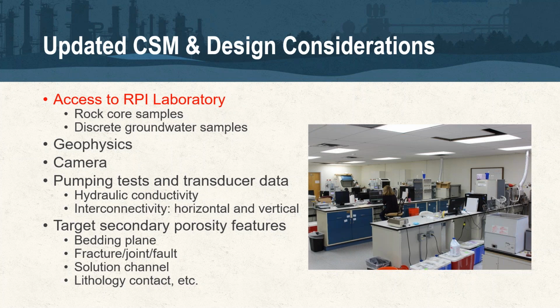And really, at the end of the day, this sets expectations. Unlike overburden sites where you can move over and continue to probe, you don't have that ability here. So going through the RDC and selecting advantageous places to put your boreholes, selecting advantageous or specifically characterized intervals to do injection is extremely important. So again, I just want to emphasize last week's presentation is a very important piece of today's presentation.